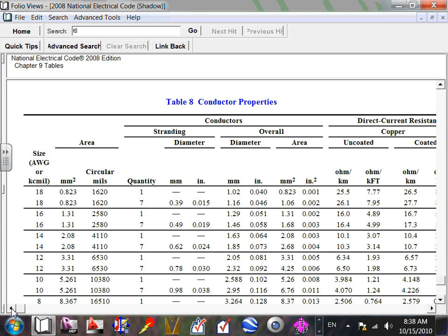Why do we care about voltage drop? If you have equipment rated for 120 and you give it 100 volts, do you think the equipment, if it's not running, is going to start? Might not start. If it's starting, it might malfunction. If it started and does not malfunction, it will actually run inefficiently.